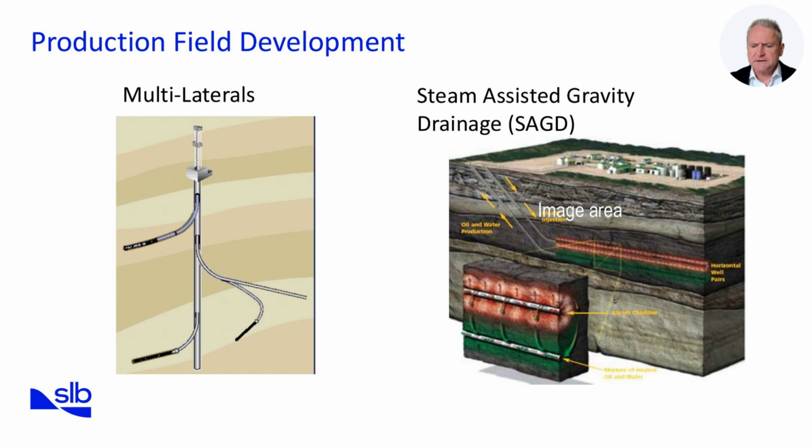Multilateral wells that exploit vastly diverse reservoirs, as shown in this graphic, are pretty rare in the industry. Most multilaterals are designed to exploit one or two sands within a major reservoir, and thus to blend two different API weights of crude into something that is produced at optimal rates. The other purpose of multilateral wells is to get maximum utilization from the production string, where the main bore on completion is determined to be capable of producing more than the exposed formation will yield.